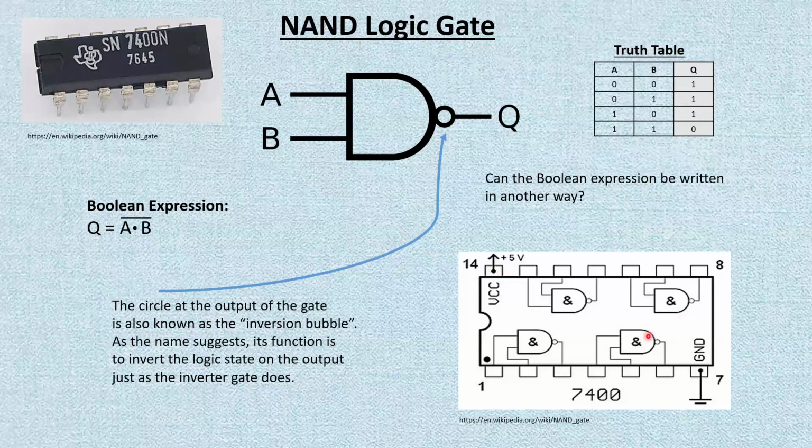Now, remember when we were talking about the PLC module and ladder logic programming, the software is interfaced with the physical PLC module, and we're going to have inputs on the left side and outputs on the right side. So with the PLC module, that output is going to be 24 volts, energizing whatever needs to be energized.